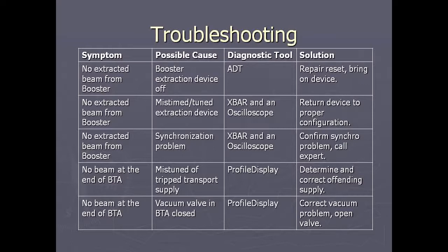And the leak setting is different from the high voltage on and off. No matter whether your high voltage is on or off, the leak parameter should always be 0. Can you set the leak parameter to like 100? Yes. Would you want to? No, you're going to ruin the vacuum and get nothing out of it. So it can be screwed up.